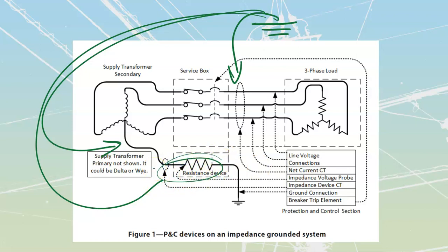And if any of those conditions are met, we're going to have an alarm that has to be activated, meeting the following standards. It has to be audible or visual, so noise or lights. It has to be labeled so people know what exactly the issue is, and it must not be able to be silenced or shut off. We don't want people ignoring these because we've lost a critical section on our system over here.